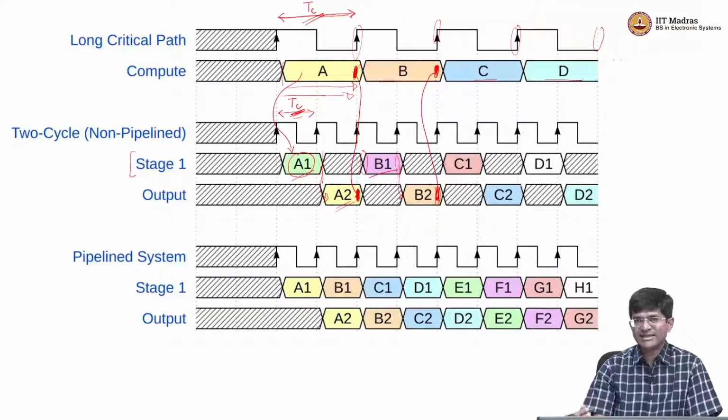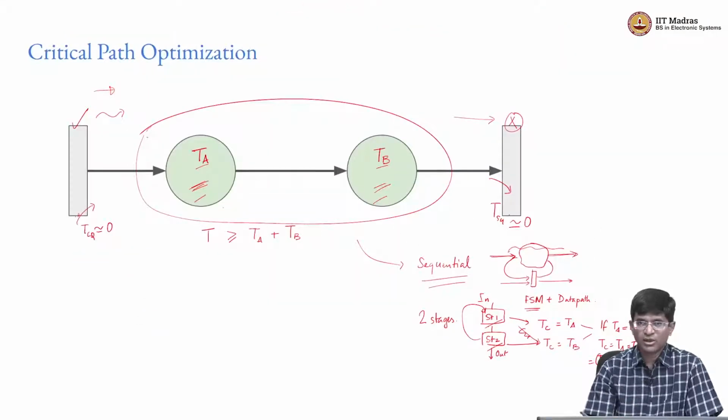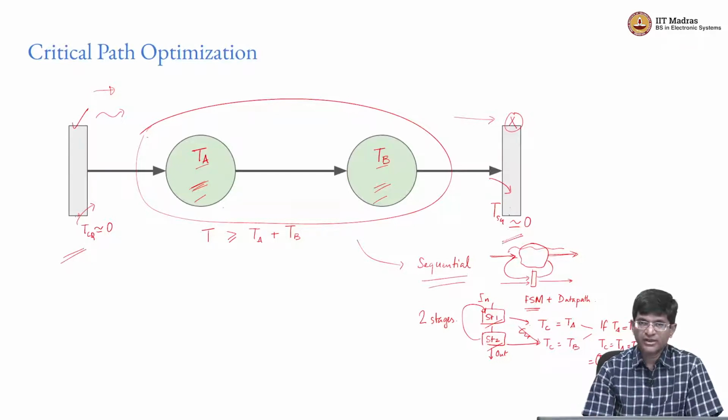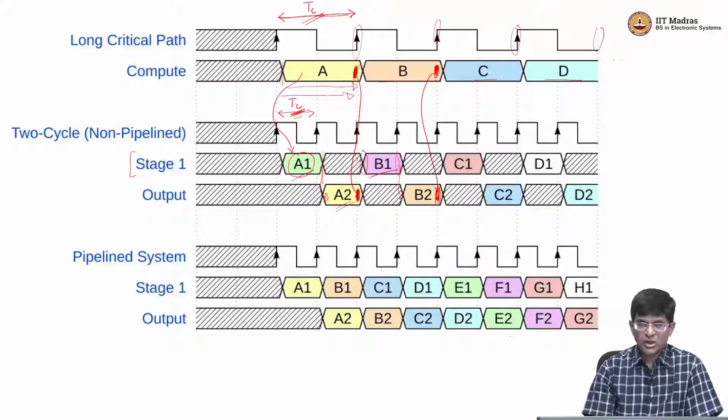So this is essentially the distinction between the single cycle and the multi-cycle CPU that we talked about, but as you can see I am not really talking about a CPU, I am talking about any general kind of digital logic where I can think of it as a path starting from a set of registers, ending at another set of registers, passing through some combinational logic in the middle. Now of course you have already seen this picture, so you must be wondering what's happening in the third set of waveforms that we see over here.